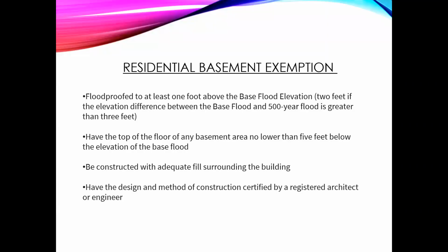And then we do have the residential basement exemption. This is an exemption from FEMA granted to a community to allow people to have residential basements that are floodproofed. It has to be floodproofed to at least 1 foot above the base flood elevation, have the top of the floor no lower than 5 feet below the base flood elevation, have adequate fill around the building, and then the design and method of construction is certified.